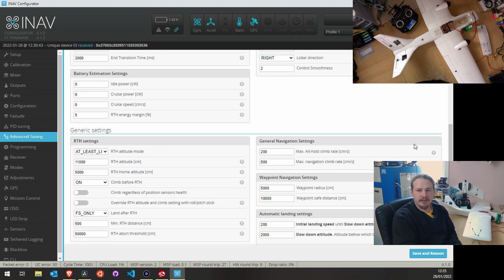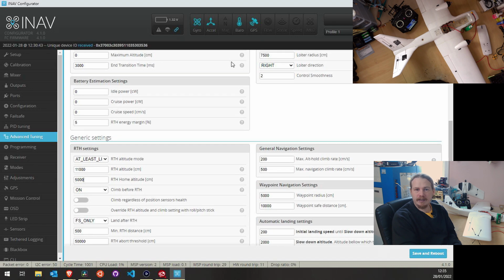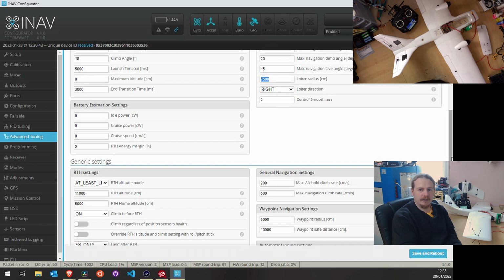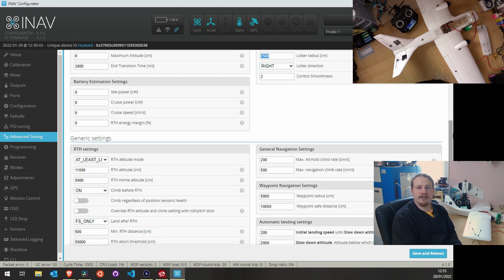The other thing that I've sort of mentioned was it's dependent on your loiter radius. So default loiter radius is 75 meters. For you to land, you need at very least a 150 meter circle on the ground with your arming point in the center. You can use safe homes, so you can set it up so that on failsafe only it will use a safe home, which is a better option if you don't have the area around you.